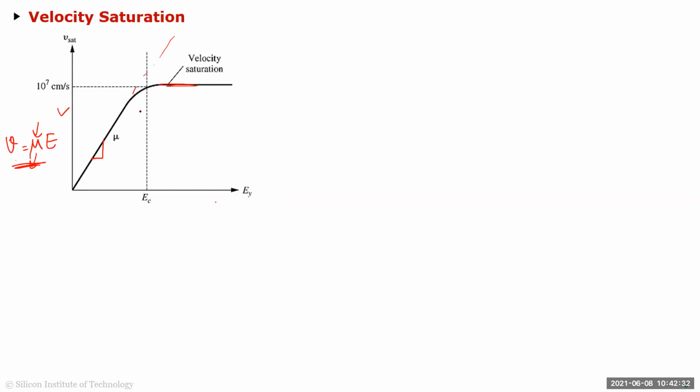So it's like a terminal velocity, a second order terminal velocity. So mu is already a terminal velocity, this is on top of it. After some time your velocity just saturates, doesn't matter what your electric field is, and that electric field we call the critical electric field. Okay, critical electric field. So EC is that term.